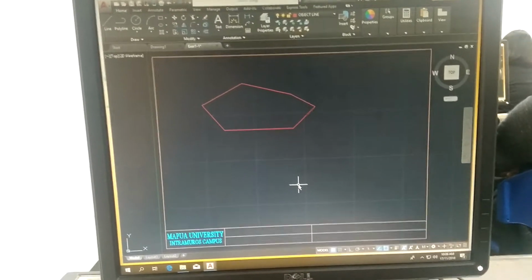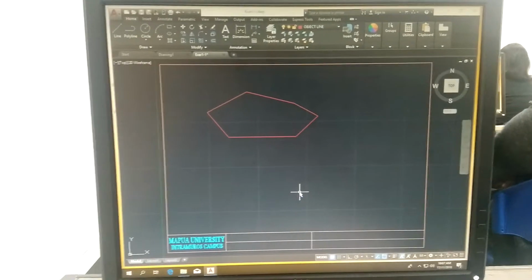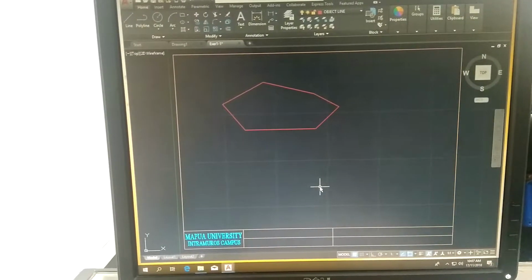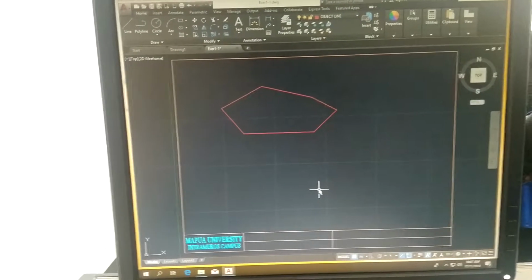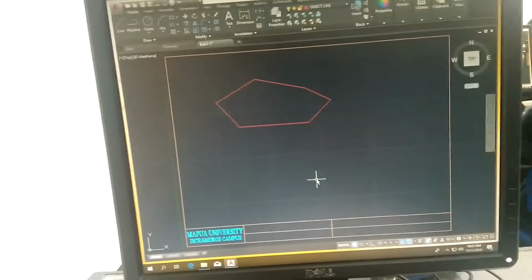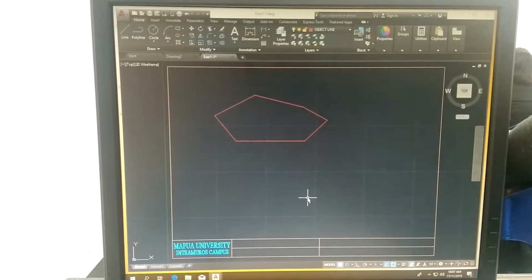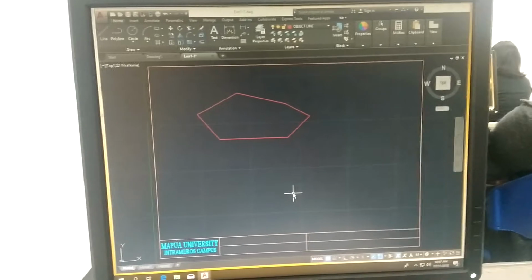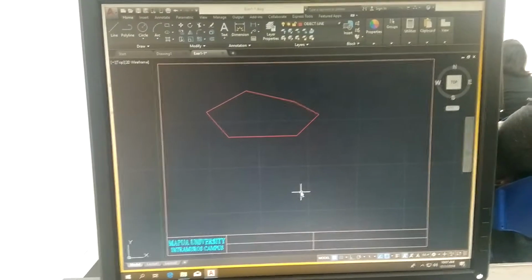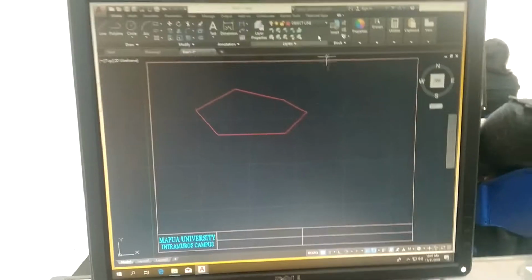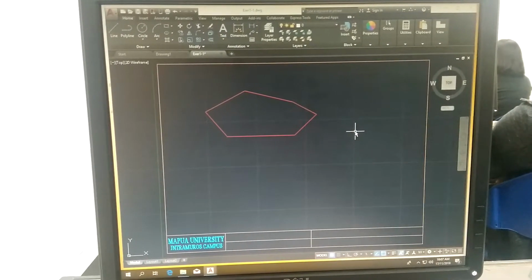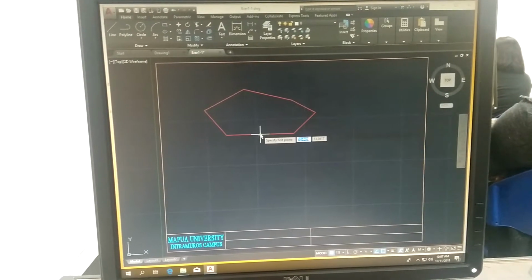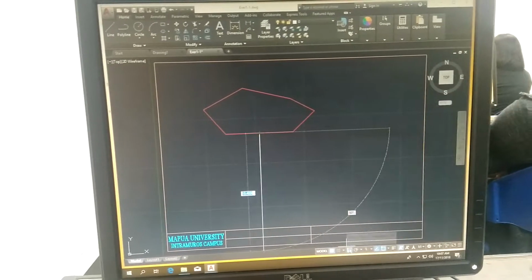Space bar. Now, the next problem is this cylinder. It has a distance from the ground, from the base, going to the two centers, which is 2.14. But there is no location at the side. Any problem you encounter, the location is at the center. Now, how? In this case, I will be using temporary line. One, line from midpoint. I will turn on ortho mode.